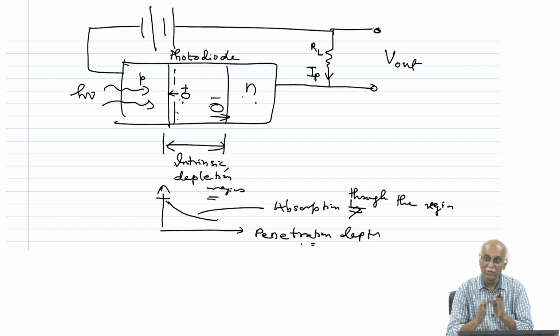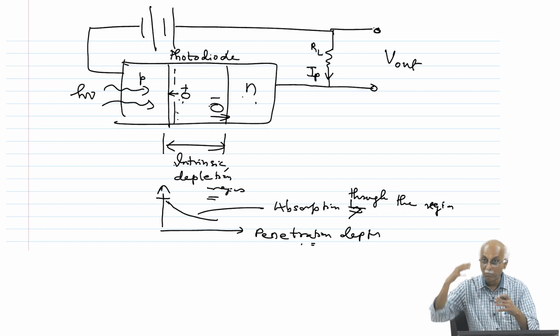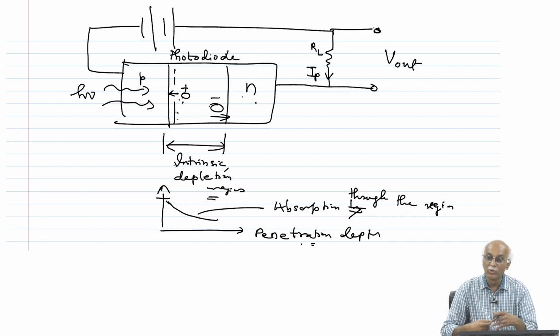Over and above, the reverse bias increases the width of the depletion region, so indirectly the number of photons interacting will also increase. So it will allow a larger output current. There are various ways of thinking, but the simplest thing is that the depletion region and the amount of photocurrent you want to measure will decide.